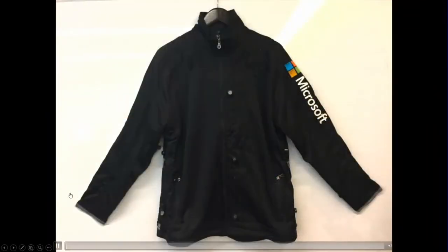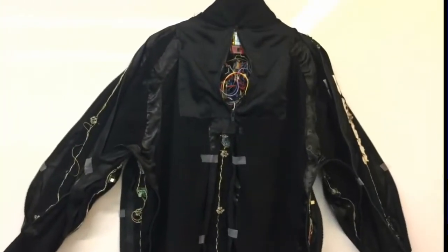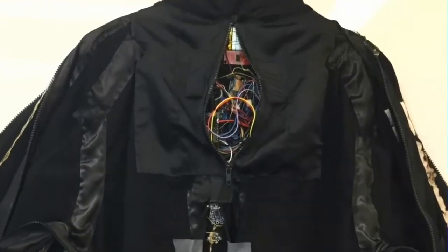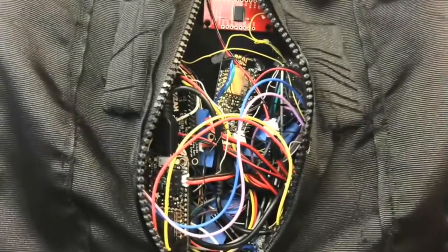The jacket contains 20 IMUs and 8 infrared sensors. Each body segment is covered by at least 2 IMUs. Infrareds are placed between the torso and sleeves. All the wirings are covered by an extra slip layer inside the jacket. Because of the sensor density, 3 separate CPUs are pulling the data and sending them with UDP packets.